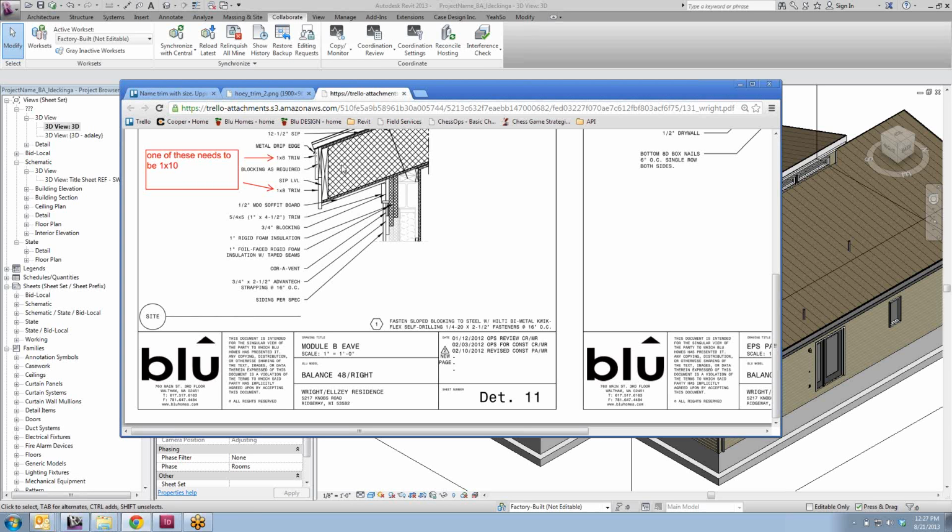And I don't know, Kevin, you might know better than I. Do you know how many different depths of SIP we use? Only two. One's 10 1/4, one's 12 1/4. And are they both for sloped roofs, or is one for slope and one for slab? I think all of our sloped roofs are 12 1/4. It has to do with span. So like the Origin, because it only spans more or less halfway, because we have that long spanning beam going through the middle, we can use 10 1/4. Okay. Same thing with the side mods for the Breeze House.